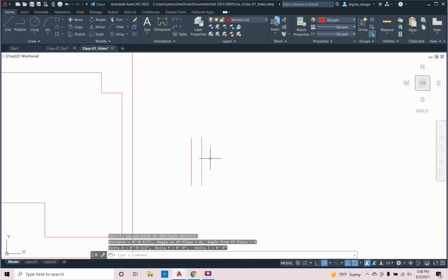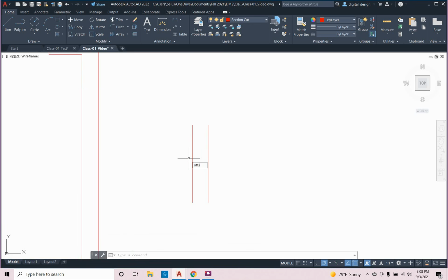There we go. There's our 1/2 inch. Okay, so that's 1/2 inch. And so the material that we're using is 1/8 of an inch thick. So I have to offset this. This is where it gets a little tricky, but just stay with me. I have to offset this 1/16, so 1/2 of 1/8.